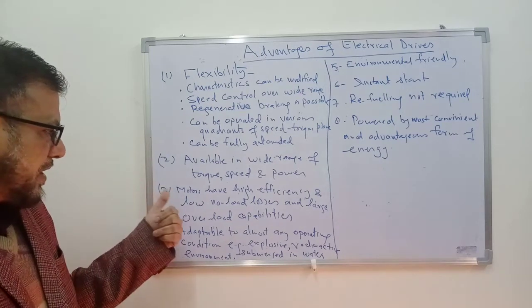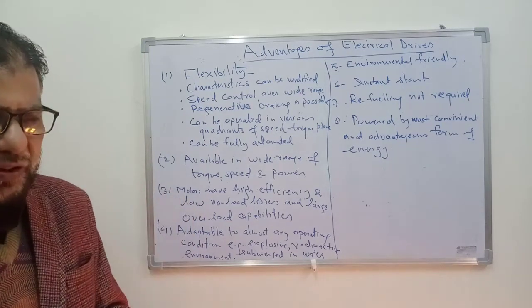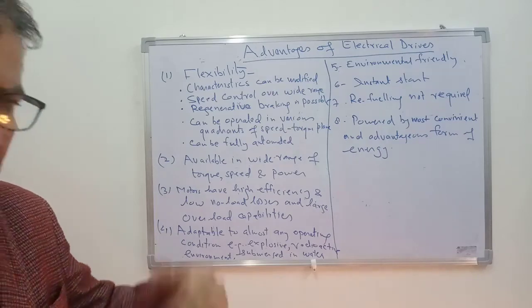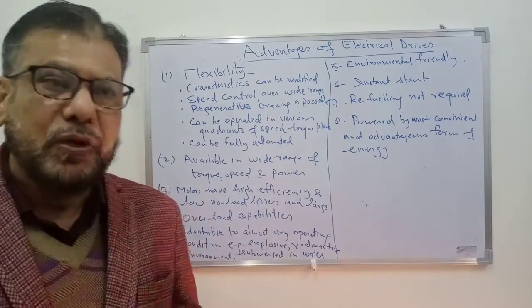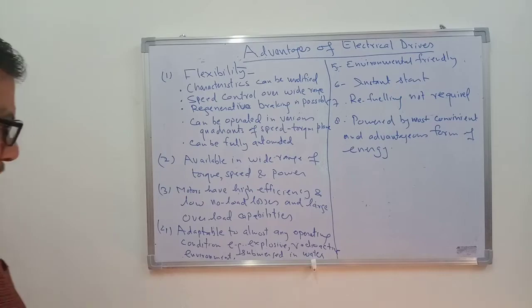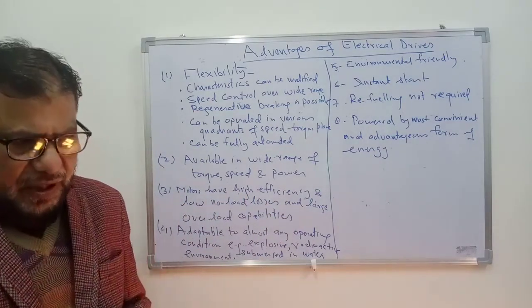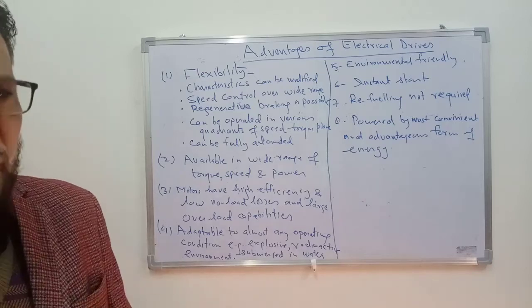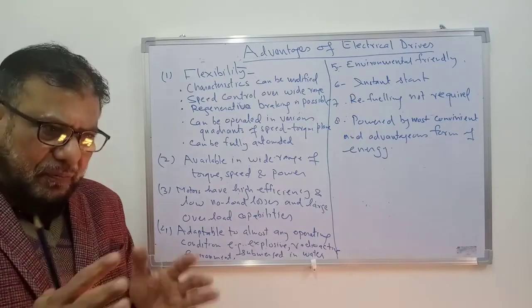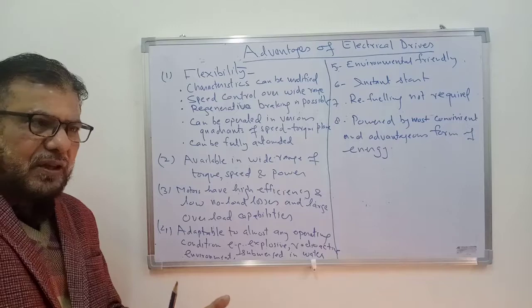Third advantage is the motors that are used here have higher efficiency as compared to the other prime movers. And also the no load losses are small. IC engines, for example, have considerable no load losses. So 50% of the power rating is usually the no load losses.